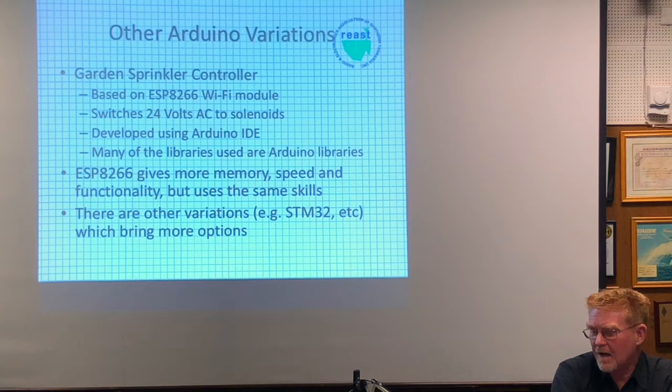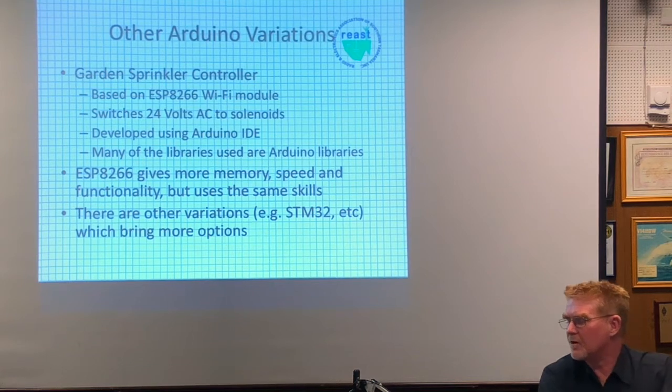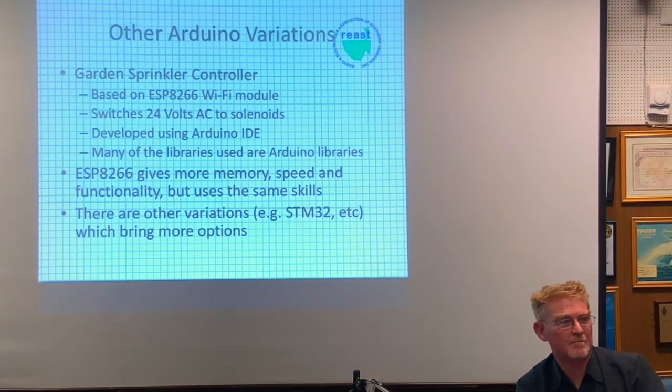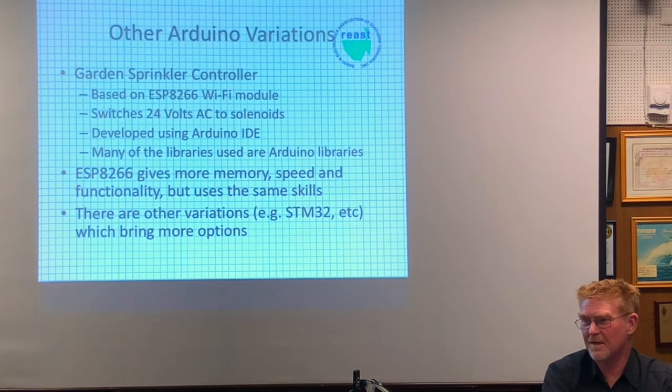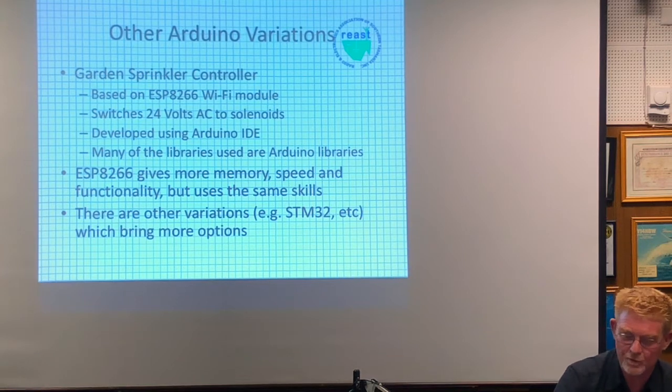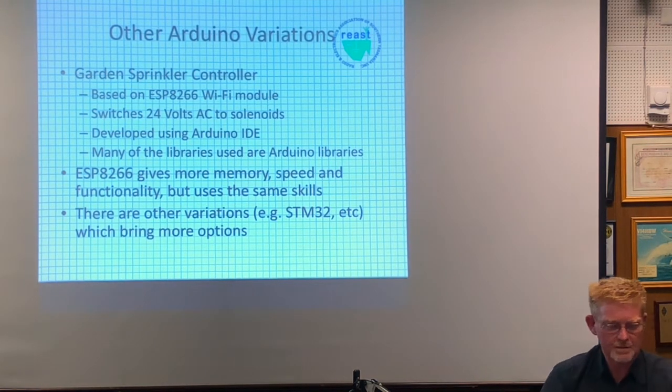I have mentioned before other Arduino variations. This is more of a show rather than a demonstrate option. That microprocessor there, like I said, 32K of program space, 2K for data. That's not a lot to do something clever. You certainly can't do anything in terms of heavy internet type activity, running a web server. This is something that can.